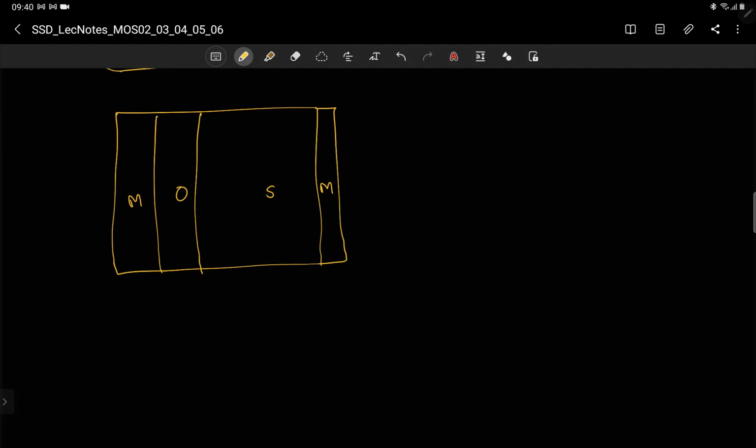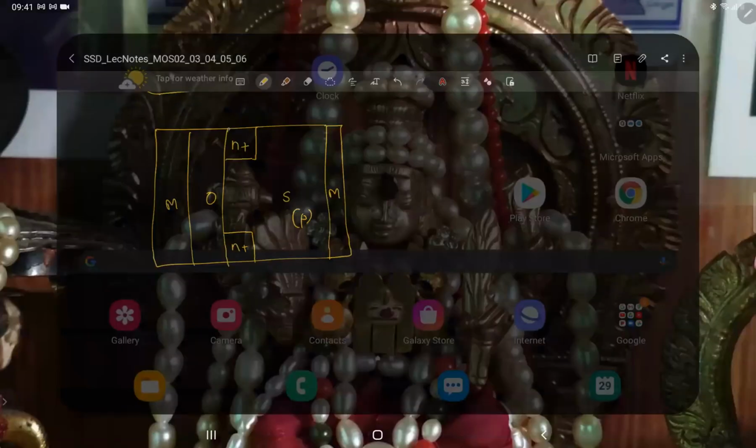So it is electrons here, because this is a p-type semiconductor. Since these are electrons that I have to contact, I will have to make a small portion of silicon here, very close by, and dope it heavily in this corner as N plus. So here also I will dope it and make the corner N plus. N plus means a large number of electrons, very large doping. Very large doping means resistance will be low, so this contact portion should not offer any resistance.